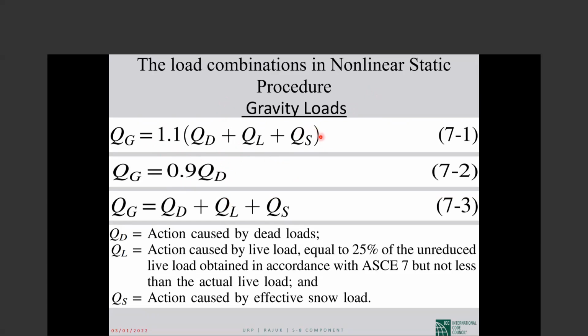So once we put this on the building and push and look at the results, then separately put the next one as a gravity load and push and look at the performance of the building. And lastly this one, and then the worst case for each element is what we use for the decision making, the performance of the building.